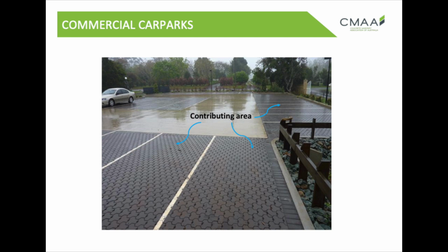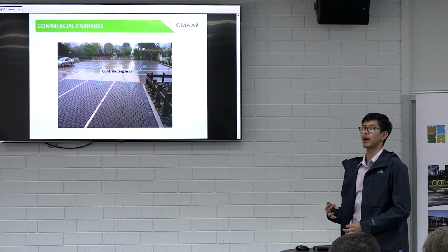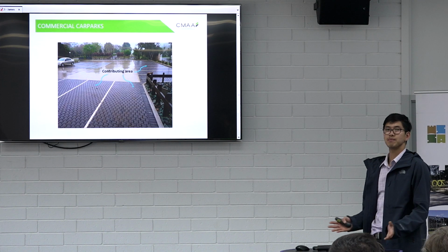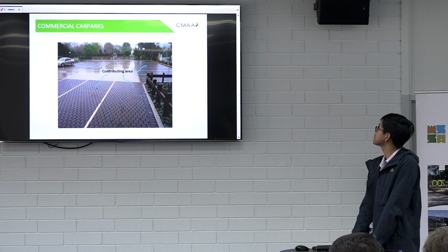And from the site visit that you saw earlier today, the entire car park wasn't paved, but instead we have a contributing area that migrates that water into the parking bays where permeable interlocking concrete pavements are used. So over here you can save quite a lot of costs.